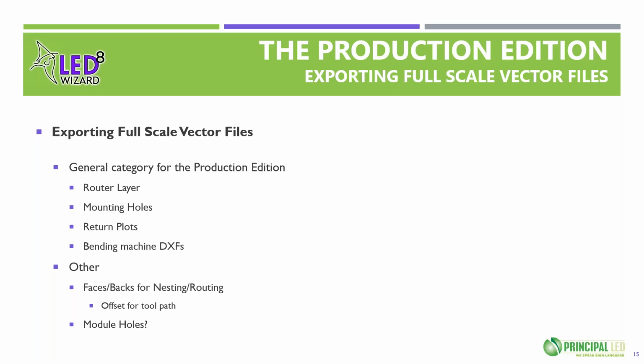And I think one of the important things to think about, if you're considering using LED Wizard for more of your production files, is to make sure that you're dealing with consistent artwork, with consistent files from the beginning. Once you start offsetting and cleaning up artwork, you start to create perhaps versions that are different. So especially if you're using LED Wizard for some things and FlexiSign for something else, just make sure that artwork doesn't change.